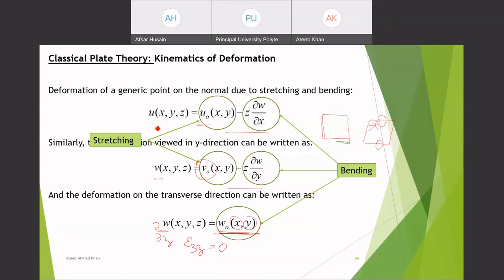And if you try to find the shear stresses at the top and the bottom surface, you will get them equal to 0 with the help of these two displacement fields. So just by looking at the displacement field, I can explain how the assumptions have been met in the derivation of this displacement field.